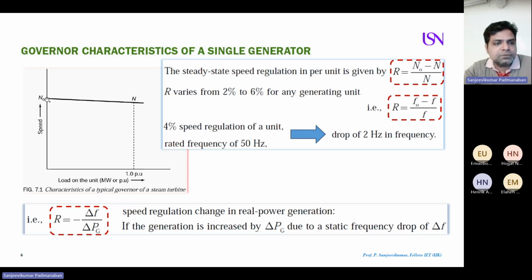If the speed of your generator is 1500 RPM when there is no load on the system, when you start loading electrical equipment on your generator, as you increase near to the rated load, the speed drops. It's not 1500, it can come down to 1420 or 1450. So a 50 RPM drop can occur. So this is a very generic characteristic of your generator.